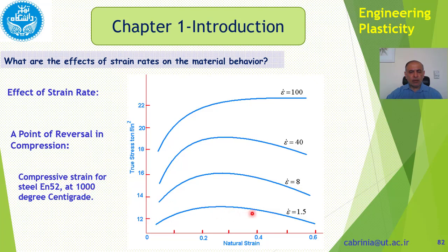here. So if more heat is released as we do more deformation, it means the temperature goes higher. An increase in temperature causes the softening of the material, and that's why at higher deformations, at higher strains, we get higher temperatures and the material softens out like this.